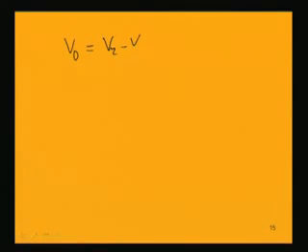We know Vz, it is given as 12 volt in the circuit, and Vbe we all know already. It is the voltage across the base emitter, and that voltage is 0.7 volt for silicon, the standard value taken even though it is not specified. So we get 11.3 volt as the output voltage V naught.